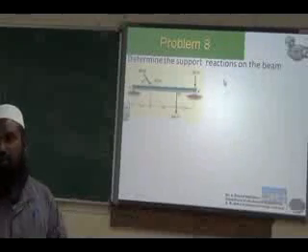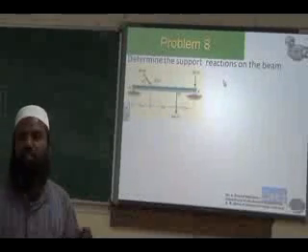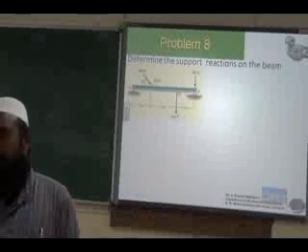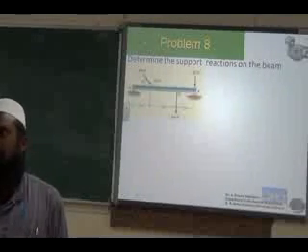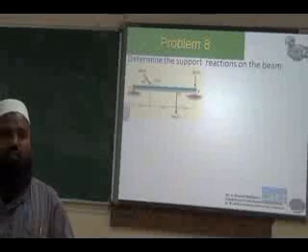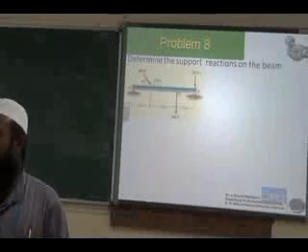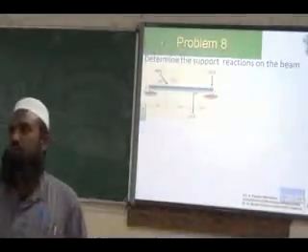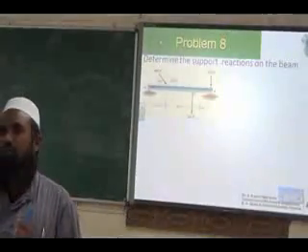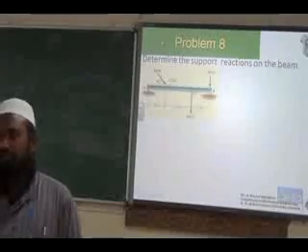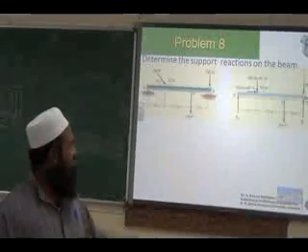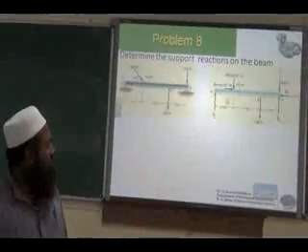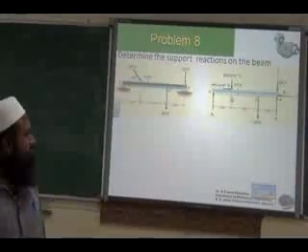It is supported at point A and point B. The support is a hinged support. If it is a hinged support, what type of reaction will we have? It can freely rotate. Hinged means it cannot be allowed to move in x direction or in y direction. So you will have two force components: force along x direction and force along y direction. You will have Ax and Ay.